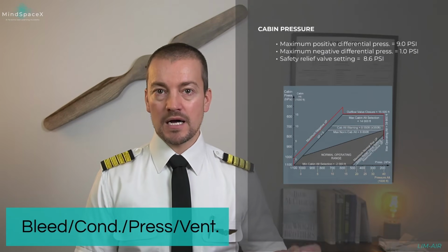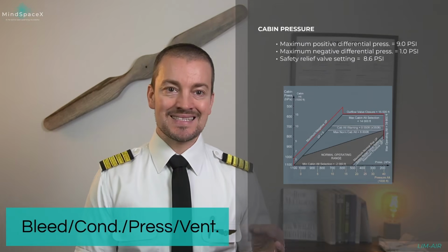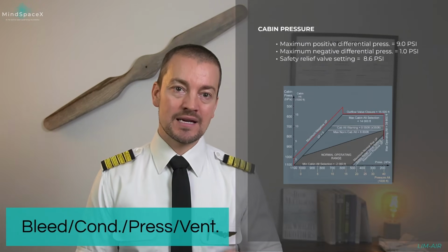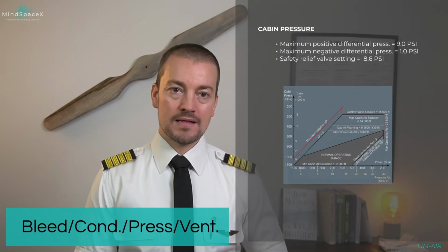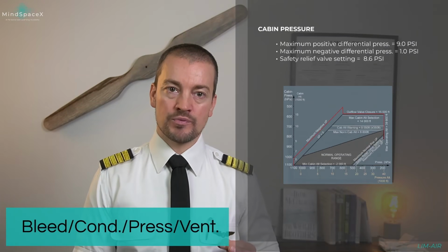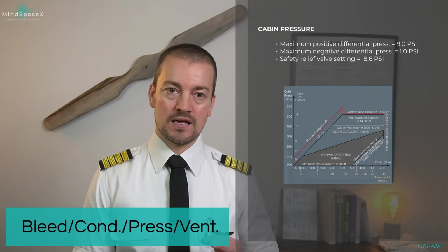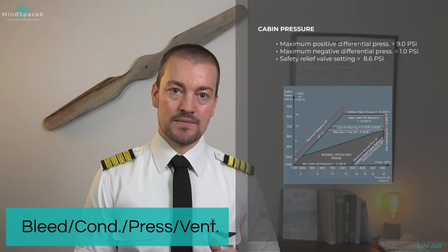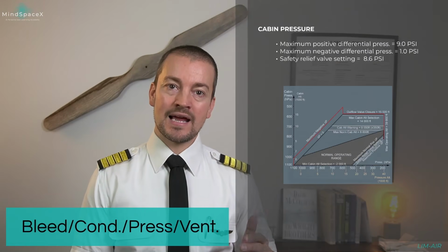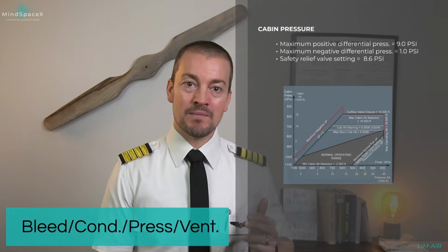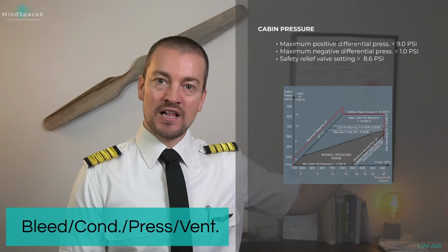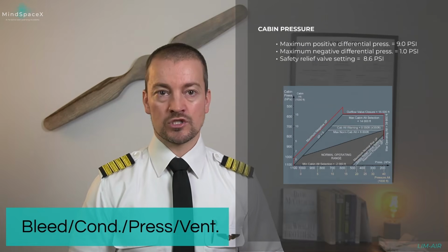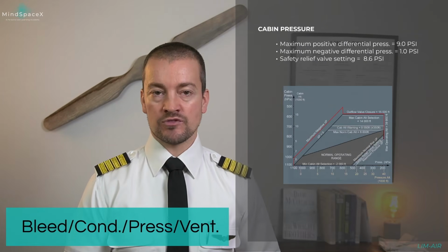The maximum positive differential pressure is 9 psi. That's with a higher pressure inside the cabin than outside. The maximum negative differential pressure is 1 psi, and that will be with a higher pressure outside than inside. It's very unlikely to experience maximum negative differential pressure, hence the value is very low compared to that of a positive differential pressure, which we always have when we pressurize a cabin.